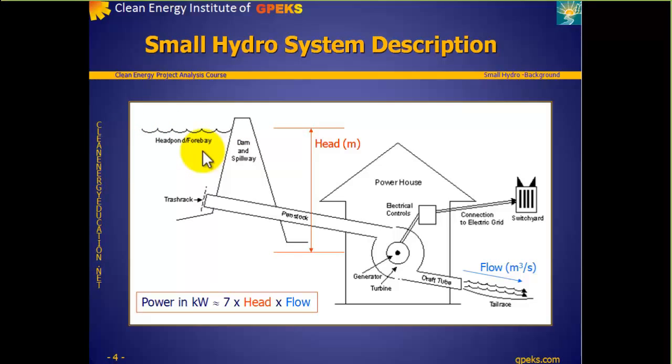An intake in the dam or diversion weir directs the flow towards a water passage. A sieve-like structure called a trash rack prevents leaves, wood, and other detritus from entering the intake. A gate of wood or steel turns the flow on and off. The passage transports the water into the powerhouse into the turbine.